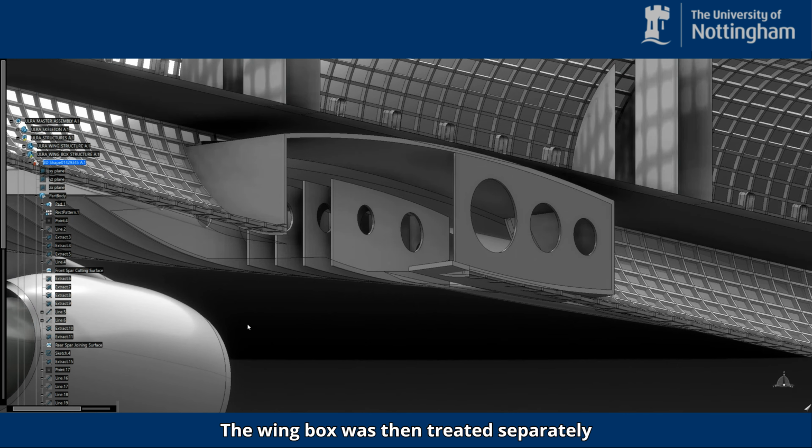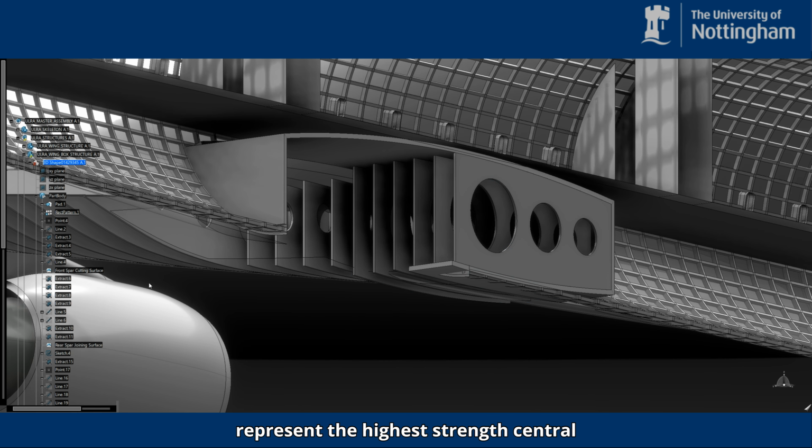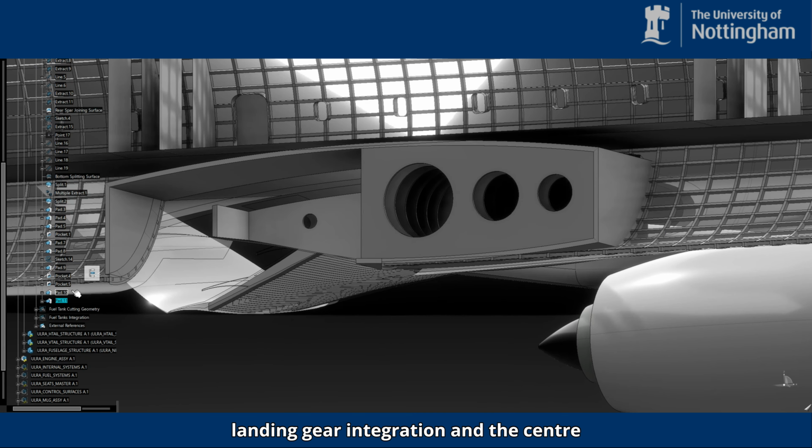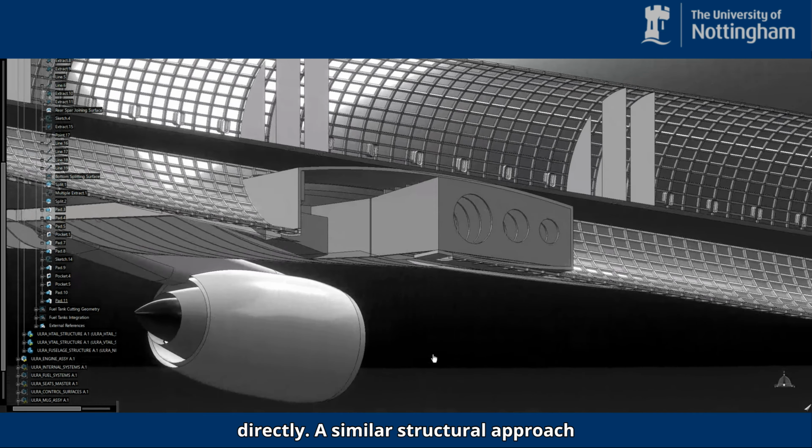The wing box was then treated separately as a more reinforced and locally customized region. This was used to represent the highest strength central structure associated with the main landing gear integration and the center fuel tank area, rather than simply repeating the outer wing rib pattern directly.